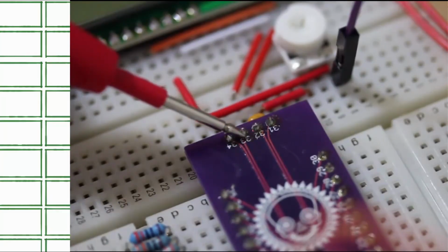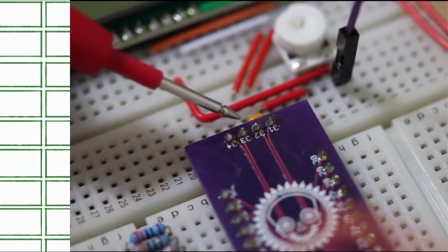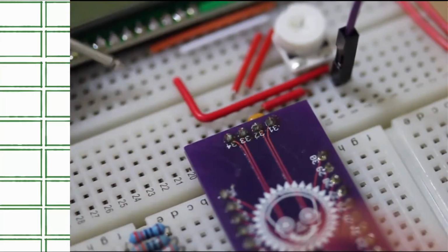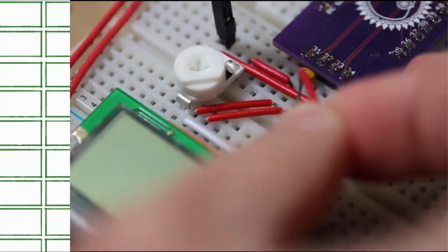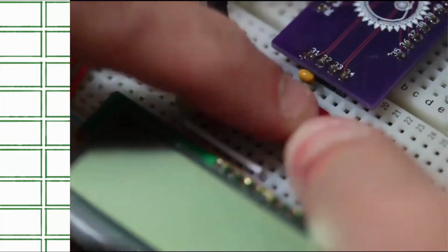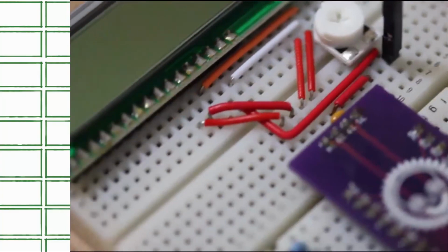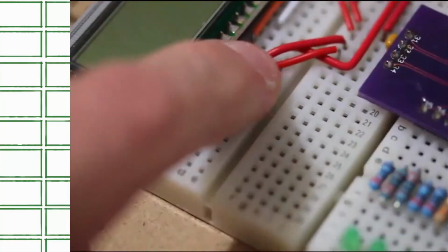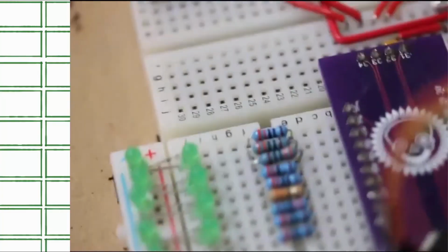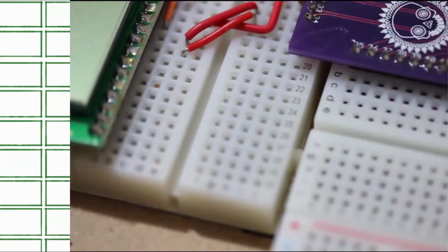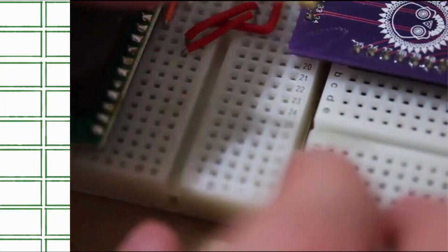33 is our next pin we can connect, and that's going to be register select. So we can connect that over to the next pin here. 33 to the RS pin. Pin number 34 to the read write pin. Okay, now we need to take all of these pins, connect them to these pins. So I'm going to take these out first. The enable will be connected from 35 to the enable.